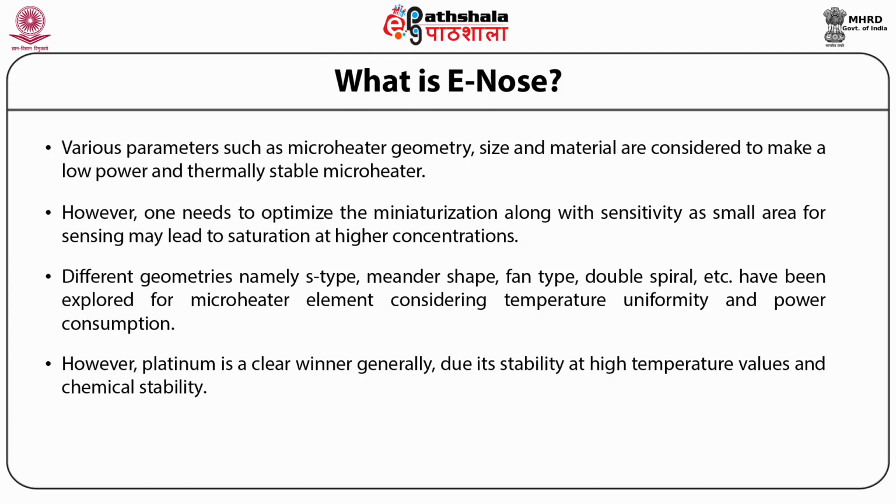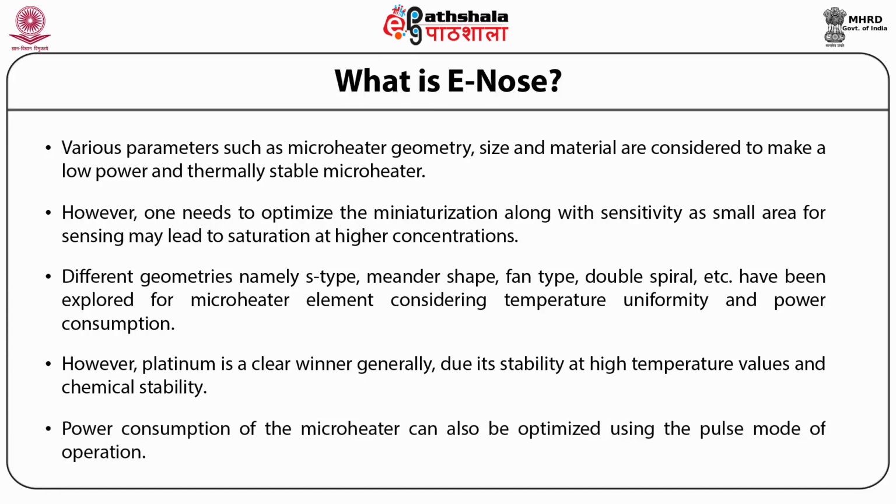Physical verification of the temperature and its uniformity is carried out by infrared imaging. Power consumption of the microheater can also be optimized using the pulse mode of operation.